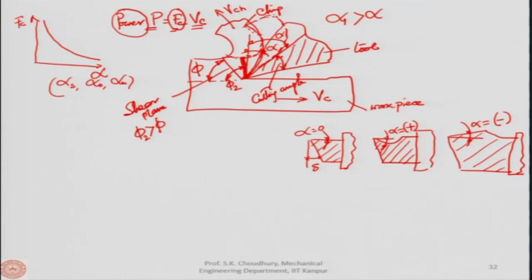All right. So, when we use, let us say, the ceramic tools, as the ceramic tools are brittle, they cannot withstand the shock, okay, or any kind of fluctuation in the force. So, in that case the tool has to have more strength. To have more strength, we need to have the tool fatter. Okay.